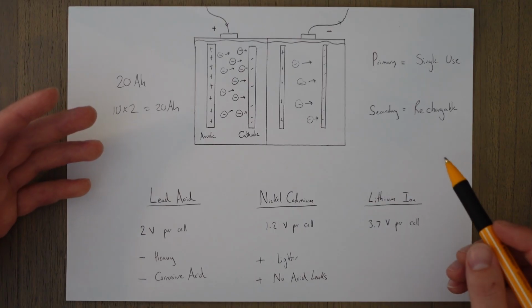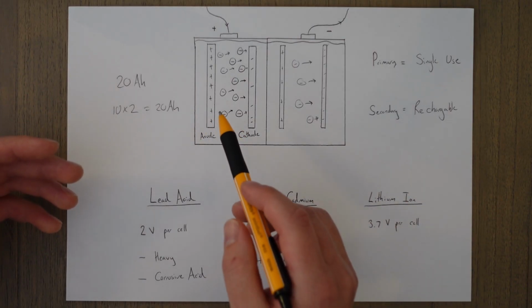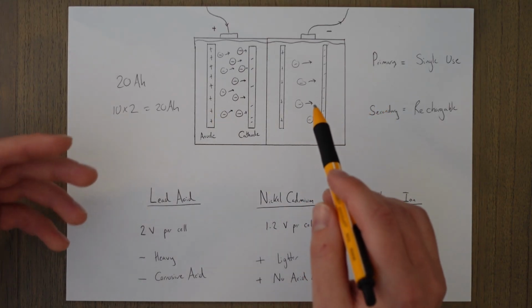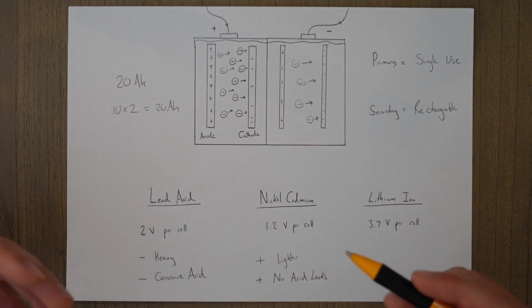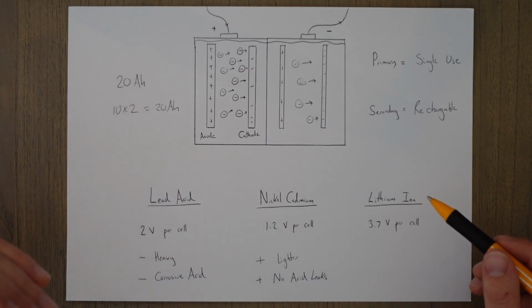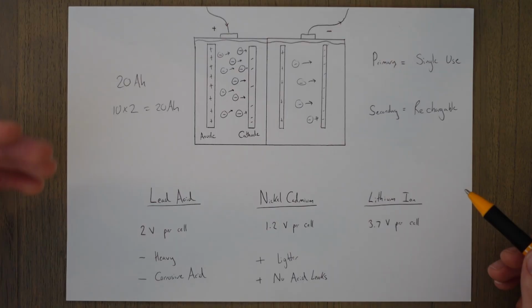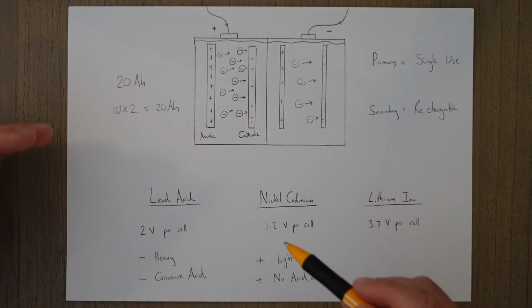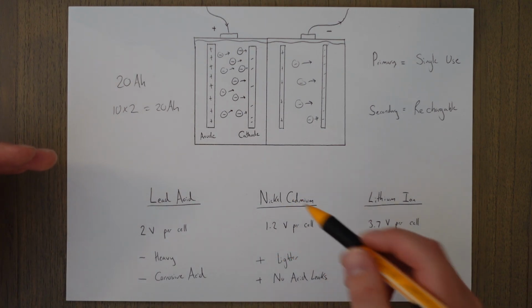You think you've solved the problem and reduced the heat in one cell, only for that overheat in one cell to trigger an overheat situation in the next cell, and so on and so on. And for this reason, these batteries must be carefully temperature monitored and placed in fireproof casings. Some manufacturers, though, see this as too high a risk, so stick to the older, more thermally stable NiCad batteries.